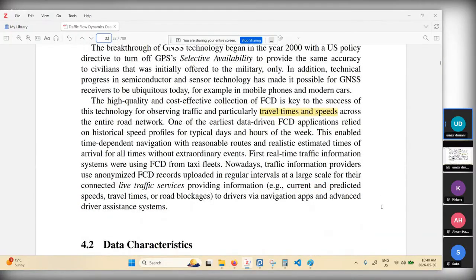And we are doing that for one vehicle at a time. But if we have hundreds of thousands of vehicles traveling at the same time, all containing GNSS technology as well as smartphones, which everyone does now, just like Google Maps, we get all of that floating car data information right in front of us when we are trying to navigate and we see that a particular stretch of road is congested. How do we know that? Through the data that is coming from these floating cars. And floating car data can also give us travel times and speeds of those vehicles in detail.